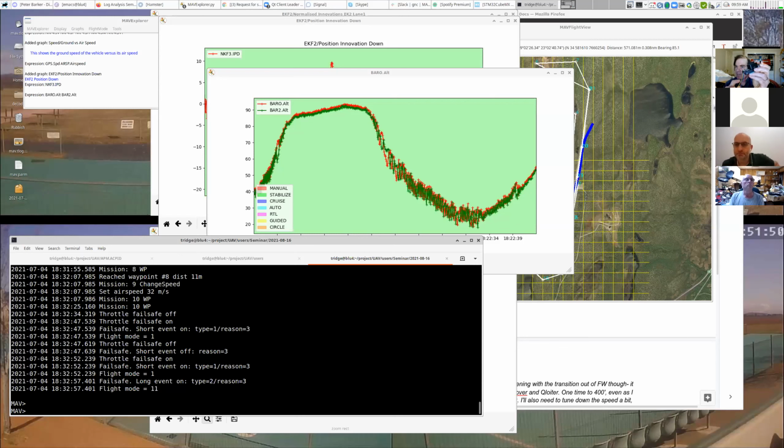So in a Cube Black, both of the barometers are inside the cube. They're just on different buses inside the cube, which means they're both exposed to the same airflow. They're not really fully independent barometers. It's great for redundancy in case the bus, the little connection to the isolated IMU, breaks. Also, one of them is closer to the heater that keeps a stable temperature. One's a bit further away, but they basically both see the same airflow over them, and so they're not really independent readings.